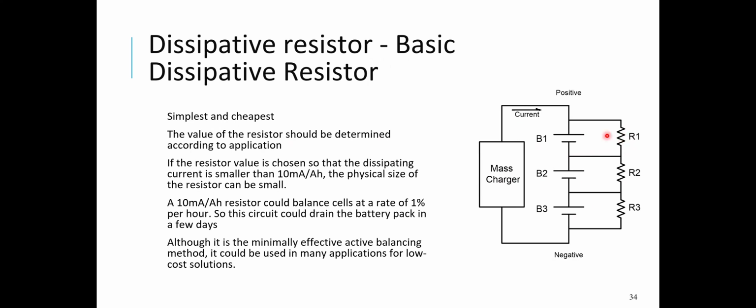So the battery that is at a higher voltage, if these resistors are identical, will have a higher current through its resistor than a battery that's at a lower voltage. So if this is 10 volts divided by 1 ohm, you'll get 10 amps over here.